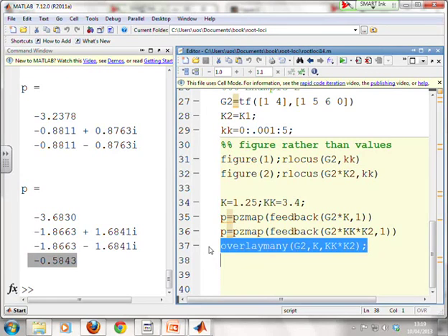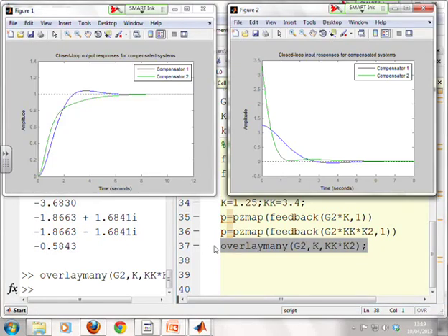So when we overlay the closed loop responses, what do you see? With the lead, much faster transient responses, this green plot, but it has actually got this extra slow mode in this particular case, which is a bit slower to settle. And that's not something we want to look at in detail here, but what you've got is this faster transient response and a good smooth behavior.